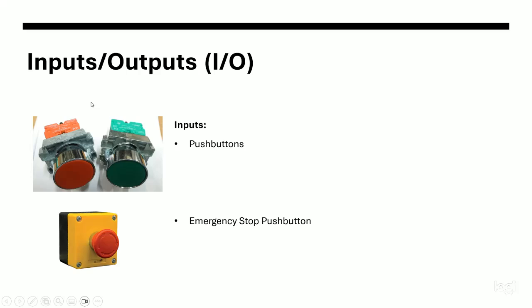Let's say, for example, you are trying to actuate a cylinder and you use a start and a stop push button. But let's say you have a bistable 5-way valve. With a bistable 5-way valve, your cylinder is going to fully actuate even if you press the stop push button, since the signal is latched and it doesn't need power to be cut for it to move to the other side. But the emergency stop will stop the cylinder from advancing at that instant.